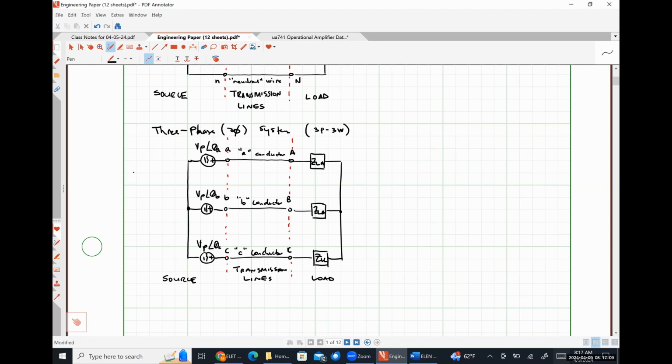And each one of those large containers is going to have a three-phase HVAC unit. Well, that three-phase HVAC unit is kind of a misnomer because the compressor is actually a single-phase load. Okay. So part of my job is to go through the system and say, hey, for every third unit, we're going to connect that compressor across the A phase, and then the second unit and every third one after that is going to be across the B phase, and then the third unit and every third one after that is going to be on the C phase, so that overall the entire system looks balanced.